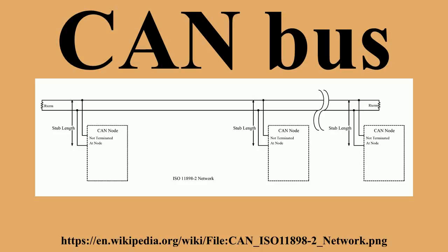This de facto mechanical standard for CAN could be implemented with the node having both male and female 9-pin D-sub connectors electrically wired to each other in parallel within the node. Bus power is fed to a node's male connector and the bus draws power from the node's female connector. This follows the electrical engineering convention that power sources are terminated at female connectors. Adoption of this standard avoids the need to fabricate custom splitters to connect two sets of bus wires to a single D connector at each node.